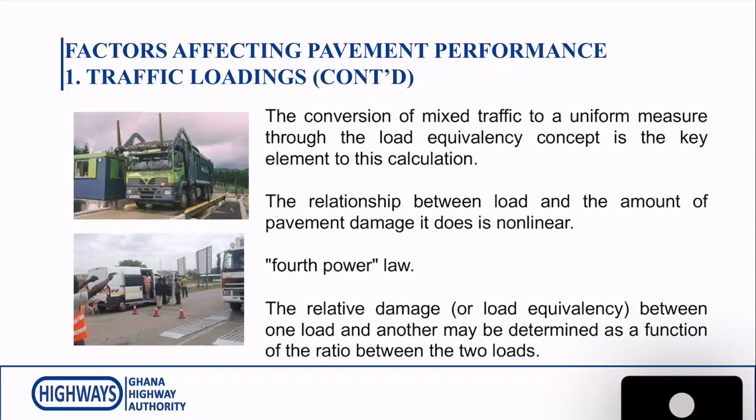Now, one has to convert the mix of traffic to a uniform measure through the load equivalency concept. The load equivalency concept is a relationship between particular loads or particular axles, and generally, we know that the damage of the axles is not linear.